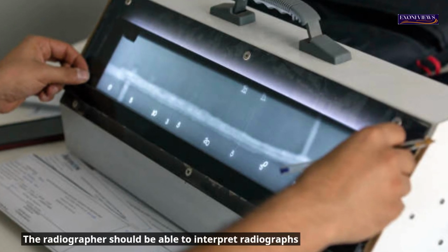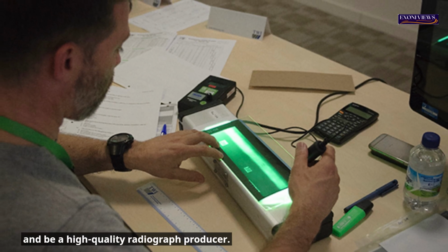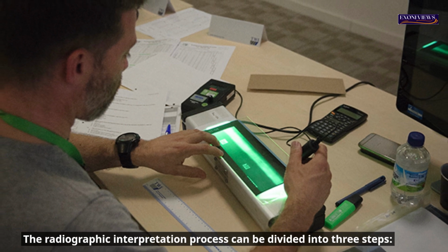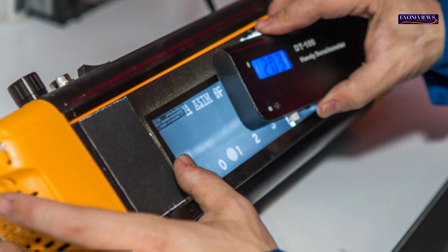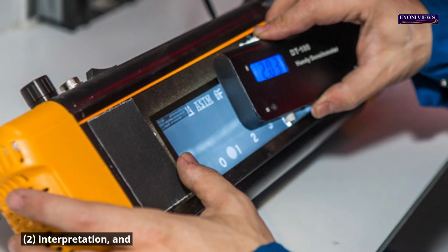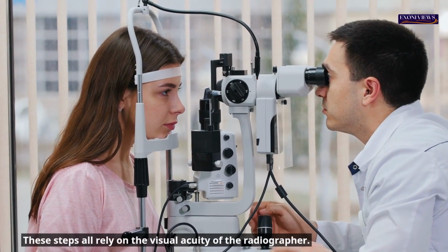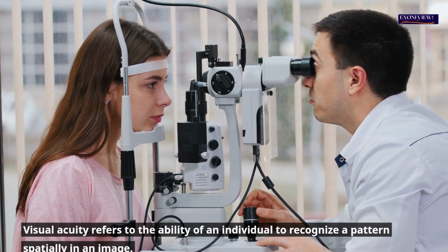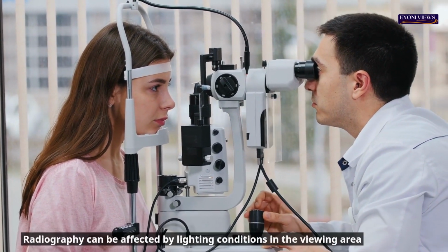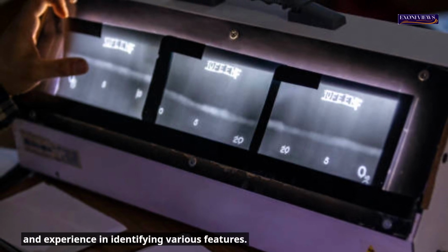Radiographic interpretation of welds. The radiographer should be able to interpret radiographs and be a high-quality radiograph producer. The radiographic interpretation process can be divided into 3 steps: 1. Detection, 2. Interpretation, and 3. Evaluation. These steps all rely on the visual acuity of the radiographer. Visual acuity refers to the ability of an individual to recognize a pattern spatially in an image. Radiography can be affected by lighting conditions in the viewing area and experience in identifying various features.